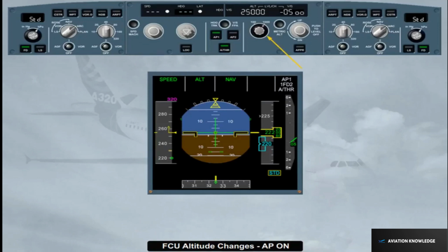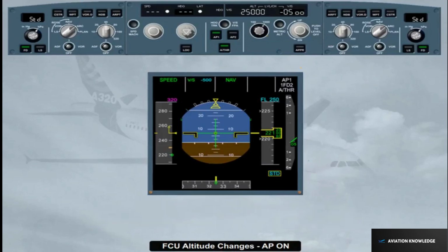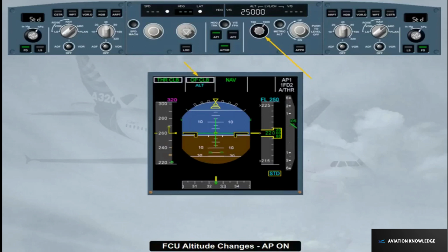The Autopilot Flight Director vertical mode reverts once again to vertical speed, with the current vertical speed value. It is now up to the pilot to decide how to regain altitude target, by pulling the altitude selector to engage open climb, or by dialing the desired vertical speed target, i.e. up to plus 1,500 feet.